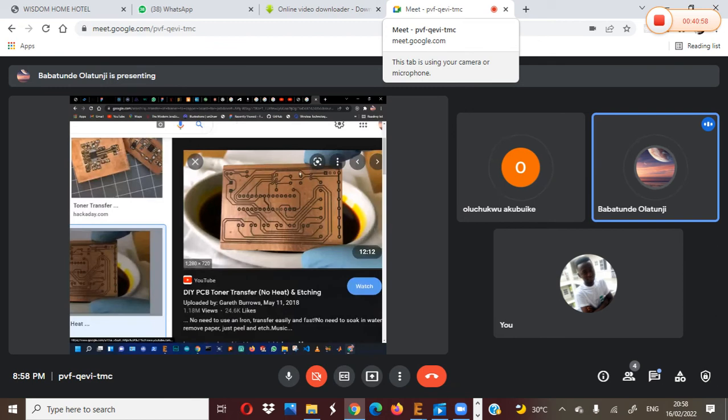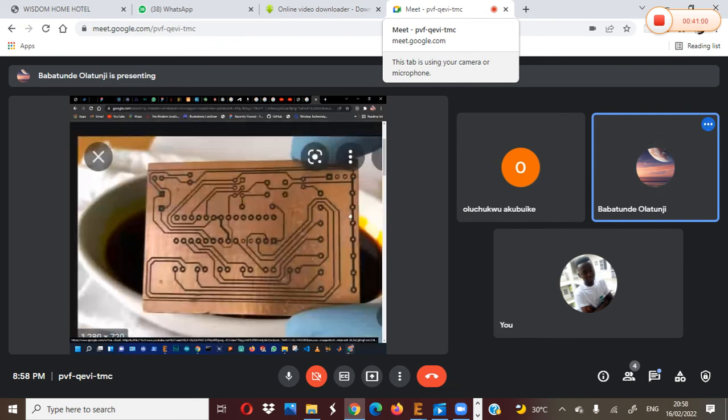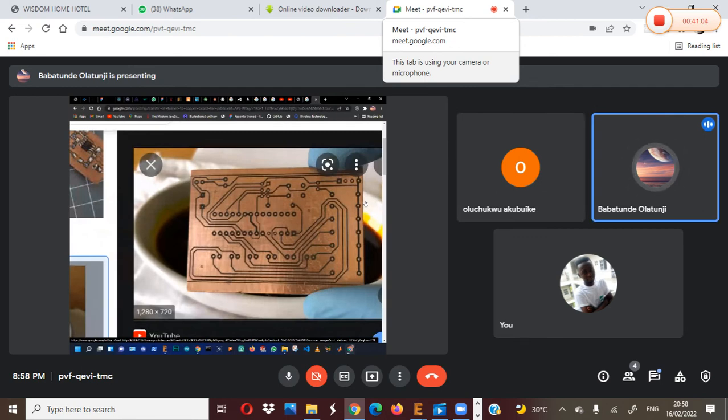Let me not use the word acid, let me use the word etchant. Your etchant could be H2SO4 or HCl, hydrochloric acid, where you can add a catalyst, hydrogen peroxide, H2O2, to your HCl.